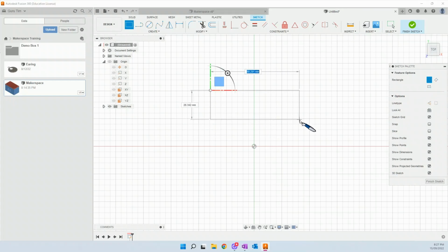It's top corner, and I'll just hover there for a moment, and you'll see that we have dimensions. So if I hit my tab key, I can toggle between those dimensions and type them in. So I could type 60 and 35, and if I hit enter at this point, that box would be set in that position. You see the padlocks indicate that it's going to be locked into that position.